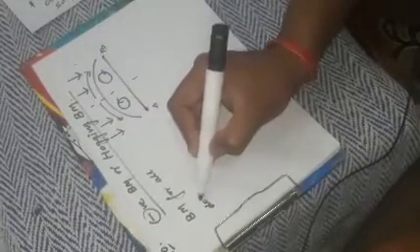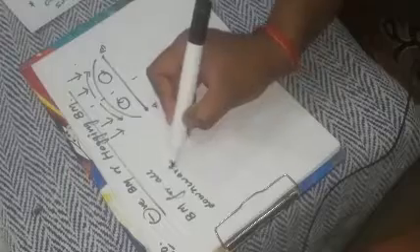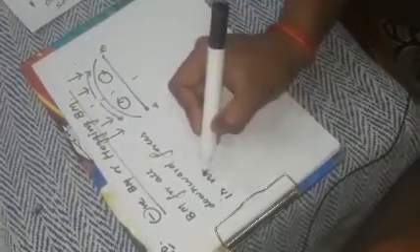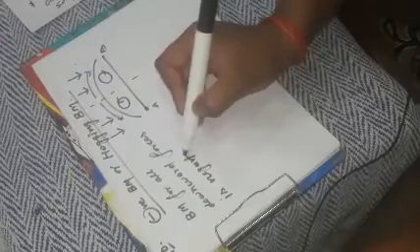So for left segment, anti-clockwise will be negative, and for right segment, clockwise will be negative. And this will be true for all downward forces. So we can say bending moment for all downward forces is negative irrespective of the segment we have chosen for analysis.